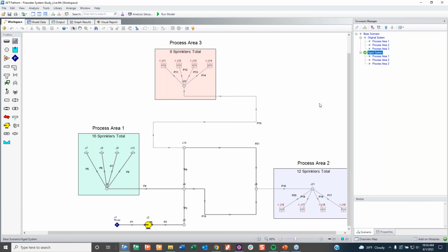So this is a part of engineering. No one really likes it, but it requires you to make assumptions because you don't always have the data, or you can't see inside the pipe. So how are we going to model an aged system? We could do a similar thing to what we did in the cooling water network, which is apply design factors to increase friction.